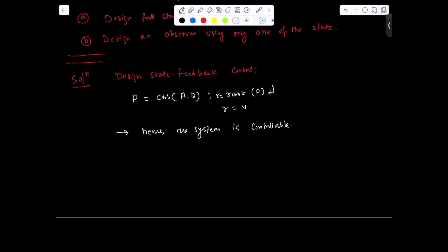For that, we can use the damp command in MATLAB. To check system stability, we can use this command, which gives omega n, zeta, and P. Omega n is the natural frequency, zeta is the damping ratio, and P is a vector which contains the poles of the system, telling whether the system is stable or not.